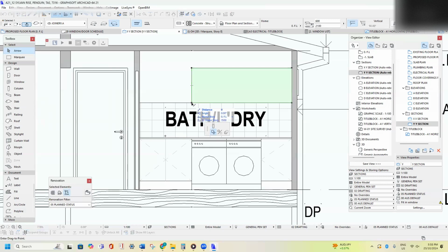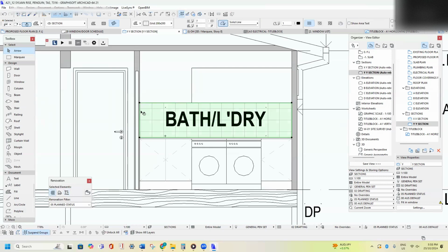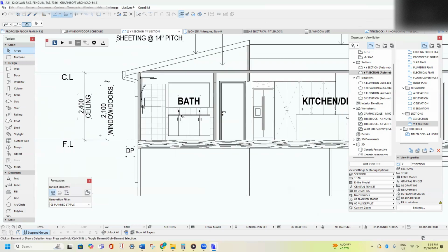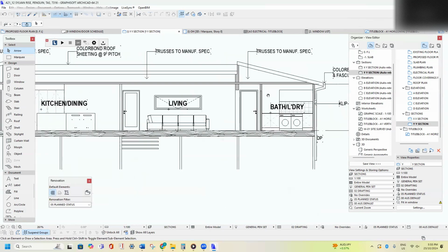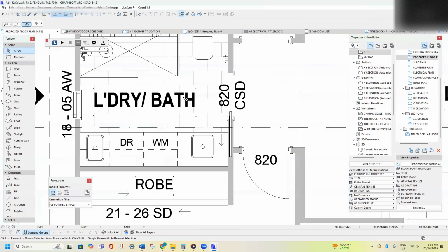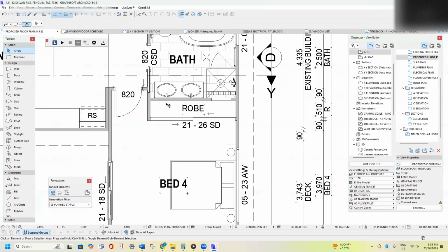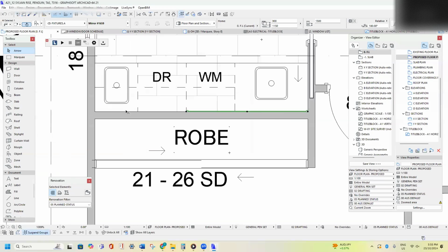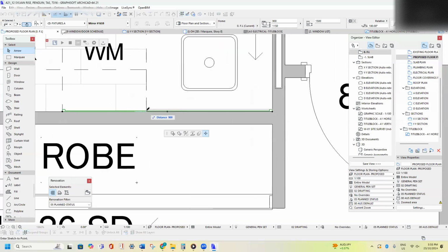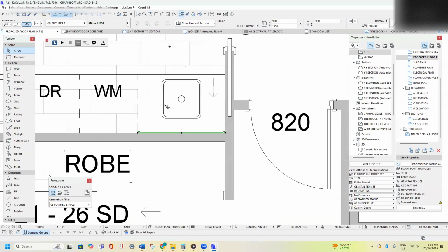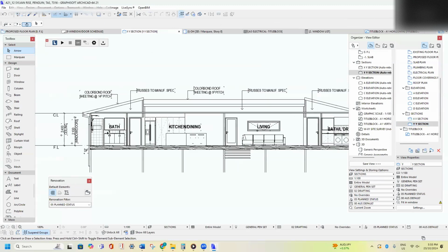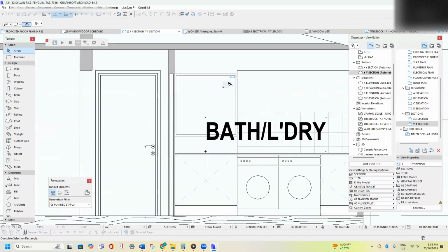And I'm not sure, there's actually going to be a mirror going above here. So what we'll do for now is drag that tiles back to there. And I actually need to put a mirror in here as well. So if I go back to the floor plan, Control Shift D, drag a copy over. And I'll have a mirror there for that portion. If I go back to section Y, that mirror is showing now.